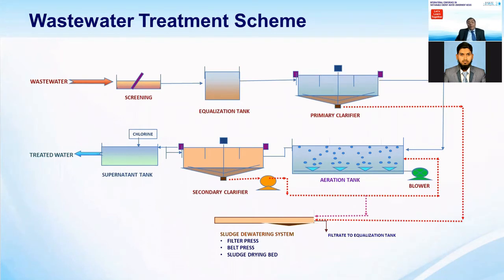There is the food to microbe ratio, normally we call it the F/M ratio, and MLSS. We have to decide how much MLSS to keep. In sewage, normally we have 1500 milligrams to 2000 milligrams per liter, and in textile, in the conventional system, I'm talking about the conventional system, we have MLSS up to 3500 milligrams per liter, starting from 1500 in denim.